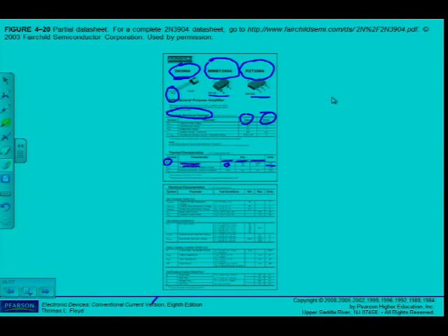So very important, I have to get this information if the transistor has to operate at higher temperatures, so that I can calculate the derated power dissipation.